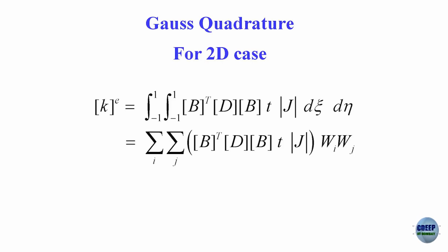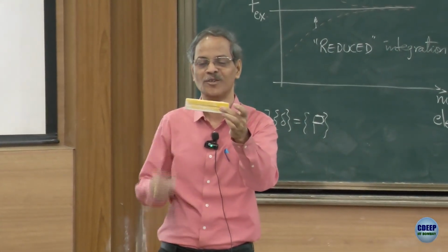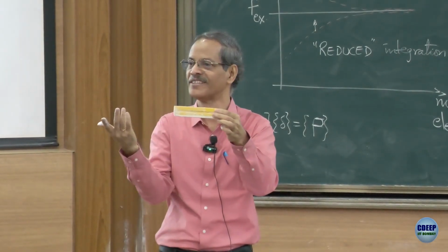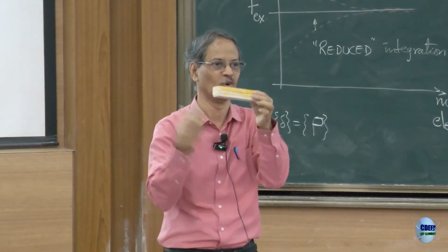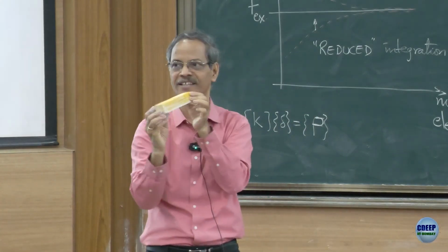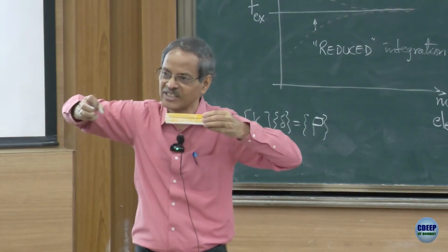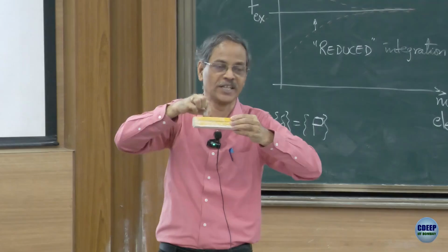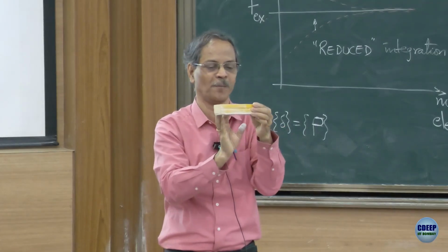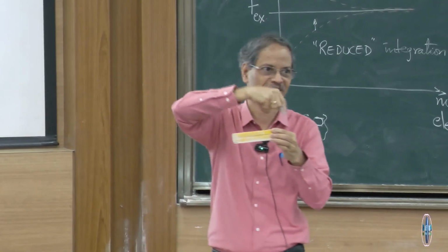Like for example, now imagine that this is the blade of a turbine or high speed rotor. Okay. So, this fellow is rotating at a very high speed, correct. So, there is a force that is acting on every mass point as this rotates at omega, that tends to pull it away from the axis of rotation.